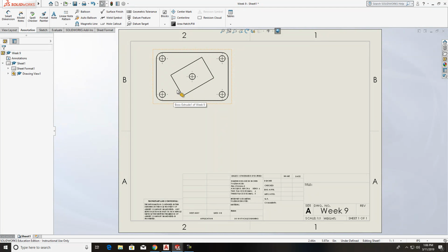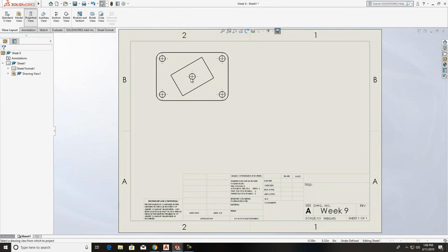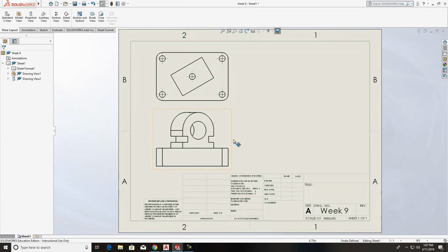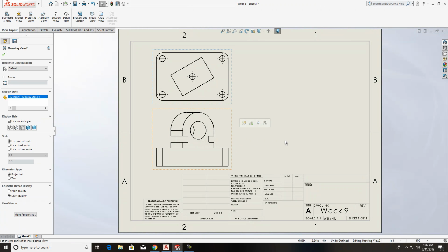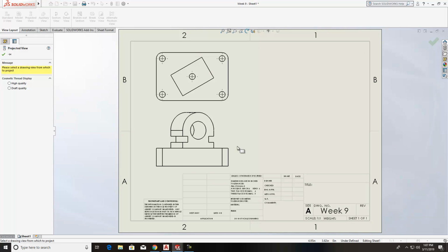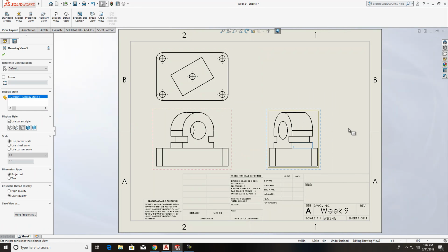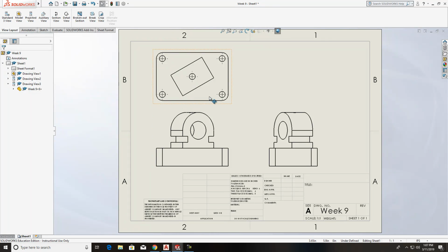Because right now, if I were to go in and project this image, this is the true orthographic way of doing it, correct? You come over here. The thing of it is, no matter how I project this in true orthographic projection, I'm not going to be able to see the face of this straight on to get the exact measurements.